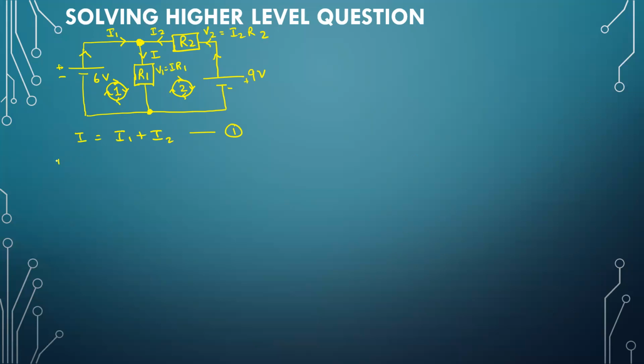Start in loop 1. Let's say in loop 1, what happens? In loop 1, through the cell, I am going up, right? I am actually going upward. Now I am again going from negative to positive. So what happens to the EMF 6 volt? I have to take him negative 6, because the rule we set there was positive to negative is plus 6. So sign convention minus.